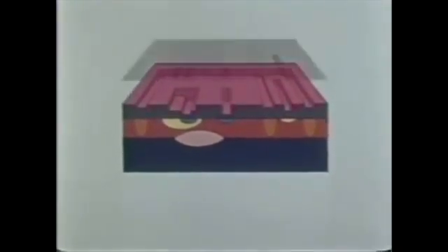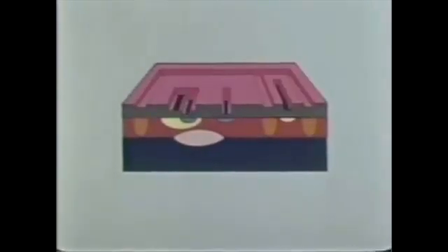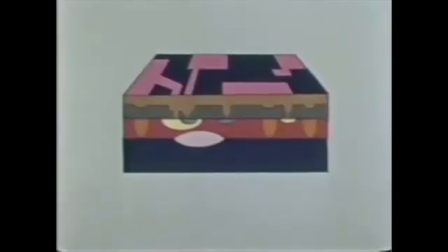The next step enables us to interconnect the various components and to make contact with them. Again, we'll etch windows in the oxide. But instead of another diffusion, a layer of metal is deposited over the entire surface of the wafer. Then, by use of the proper masks, the excess metal can be etched away.